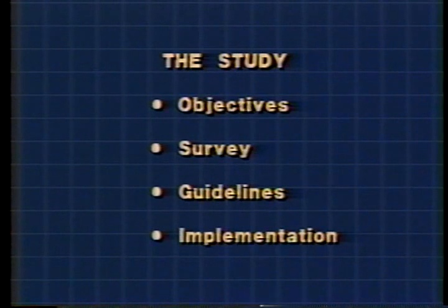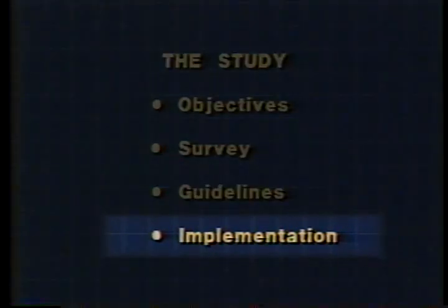The Washington State Department of Transportation made an early attempt to see how well the criteria on when to apply load restrictions worked. To do this, maintenance personnel examined pavement sections in Washington during February of 1986. This state route in central Washington had experienced a winter with a freezing index of about 1,000 degree Fahrenheit days and is classified as a thin pavement. This was the pavement surface on February 6.